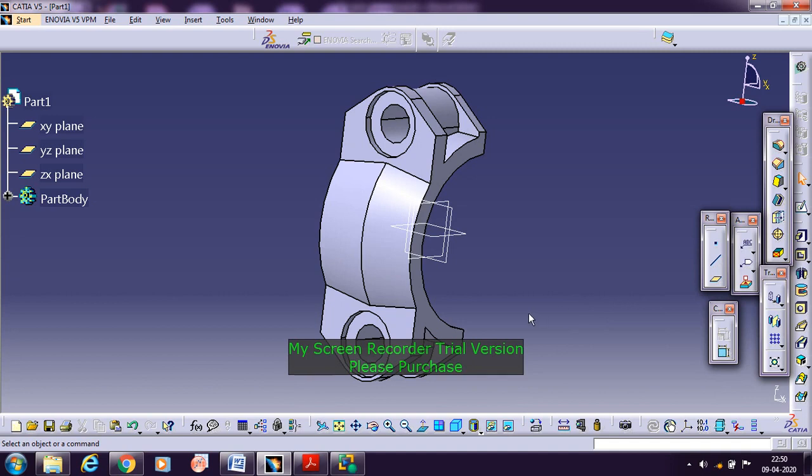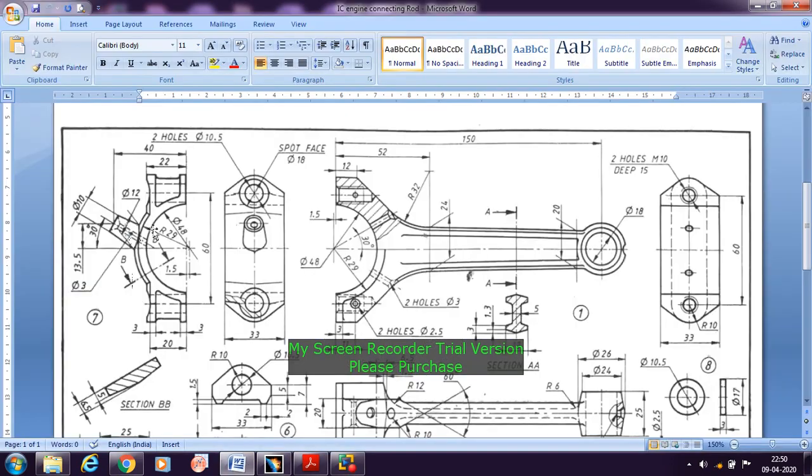Once it is done, now we can go with the oil hole here. For producing this oil hole, we need to draw one line anywhere, taking an angle of 30 degrees. Then once after drawing this axis line at an angle of 30 degrees, at the end point you need to set the vertical distance to 13.5 mm, and then the horizontal measurement to 40 mm here.